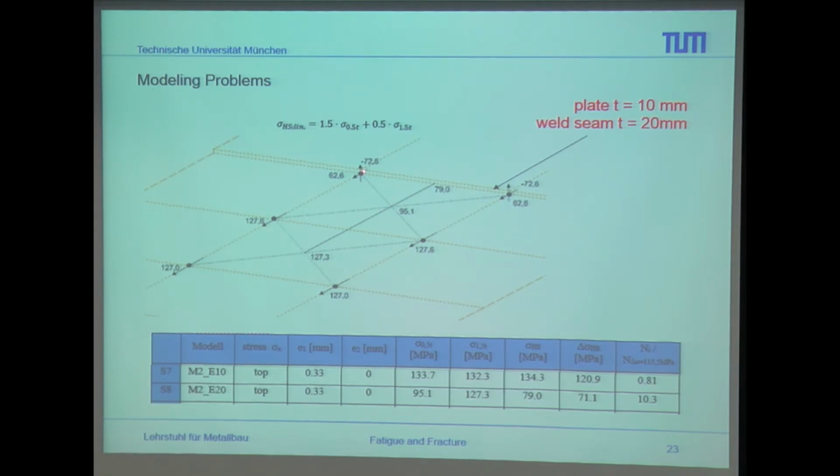And at the end, the results our program delivers are always for the structural node at this part. This node is influenced by this element, and also the two elements which have a thicker size. And due to this, we have a mean value of all 4 elements. And so we have the lowering of the structural stress, which at the end does not really fulfill our estimations.